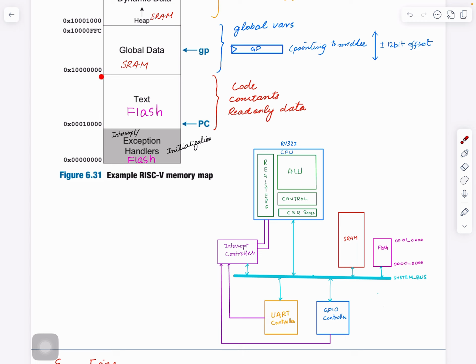Before this, the SRAM starts here. So from before this until this, whenever we put that address, it means we are reading a location of flash. The address decoder, or the scheme here, will select this device and tell it that this address is for it, and this location is then read and data brought back. So whenever an address in this range comes, the system bus will know that it is for flash, and we will be communicating with flash.